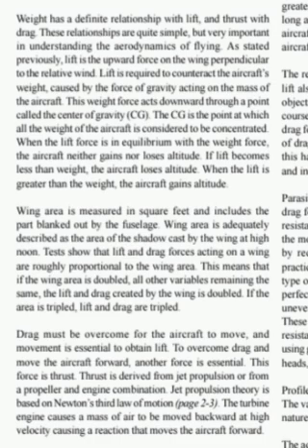If the area is tripled, lift and drag are tripled. Drag must be overcome for the aircraft to move, and movement is essential to obtain lift. To overcome drag and move the aircraft forward, another force is essential. This force is thrust. Thrust is derived from jet propulsion or from a propeller and engine combination.